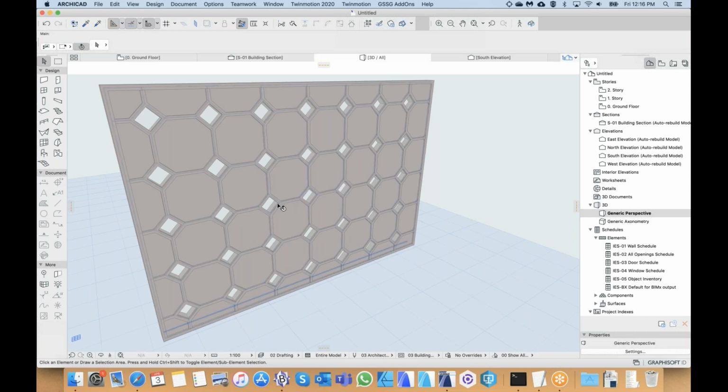If you're doing something more detailed, consider whether you need it geometry based or whether you can get by with just a vectorial hatch and a texture. So something much simpler. You need to make that call, because if you add too much geometry, then your file will be much heavier.